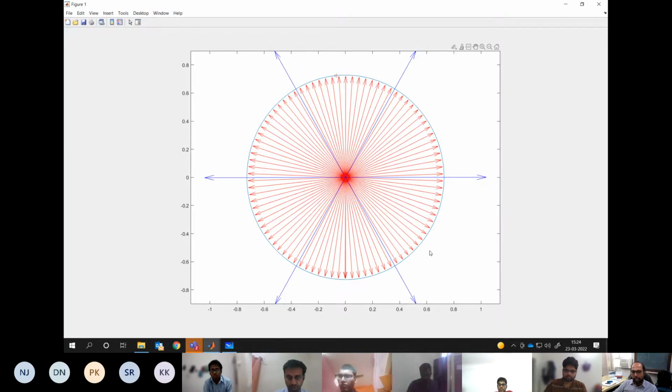Just to repeat that. The tip you see over here, the small triangle which is rotating, is basically the tip of the voltage vector which is continuously rotating as your voltage is fed to the machine or as your motor is running. We are trying to approximate this continuous rotation with certain snapshots, with certain voltage vectors taken at regular intervals.